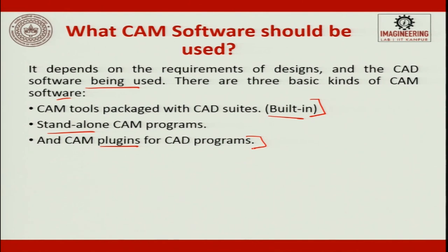Now comes the part when the software is standalone. The standalone softwares are dedicated CAM softwares. They are capable of powerful CAM operations that allow creating complex geometries like free-form geometries. But one of the flip sides is that the associativity is lost when the native file of the CAD software cannot be imported. So, it is important that your CAM software and your CAD program support the same file formats, for instance IGS, STEP, STL, whatever you pick, it should support them. These are more important.